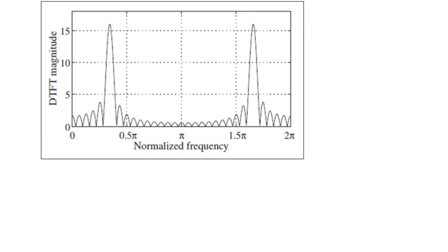To better understand the shape of the Fourier transformation as we see in this particular illustration, the two major lobes, peaks here. Let us observe that the sequence that we have shown with the help of the earlier expression, small gamma, is a windowed version of the infinite length sequence small g of n that can be obtained using a rectangular window w of n.